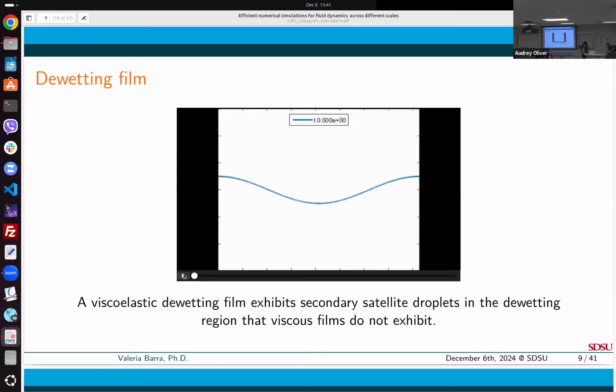However, the separation for this formulation, since the function has to be continuous, you still have, even when it separates into separate blobs, some very, very tiny layer deposited at the substrate that is called equilibrium or precursor thickness. And it stays there, and it's due to the van der Waals force that I was mentioning earlier. So this is an evolution in time. So this surface is just perturbed and it separates into different blobs or patches of fluid.